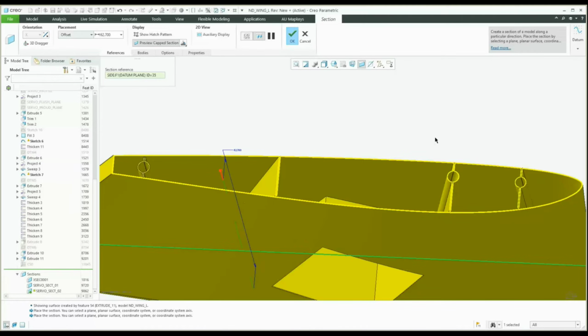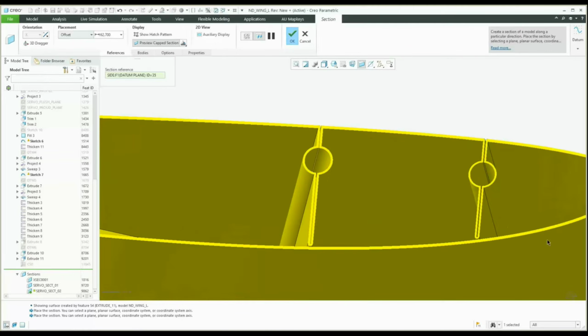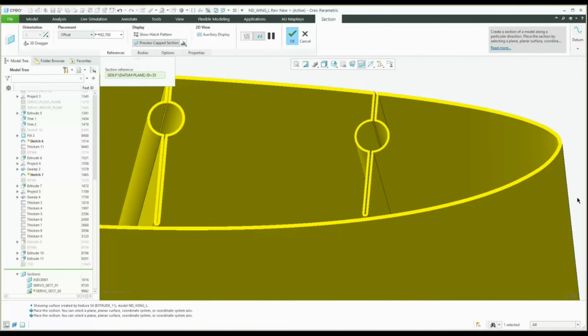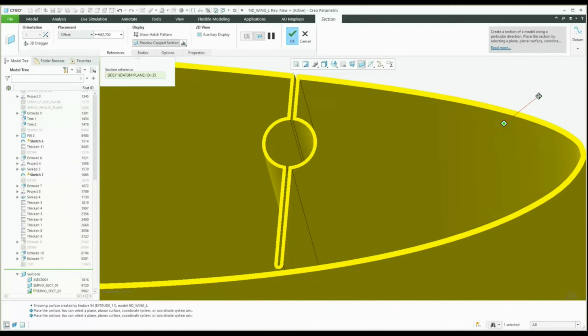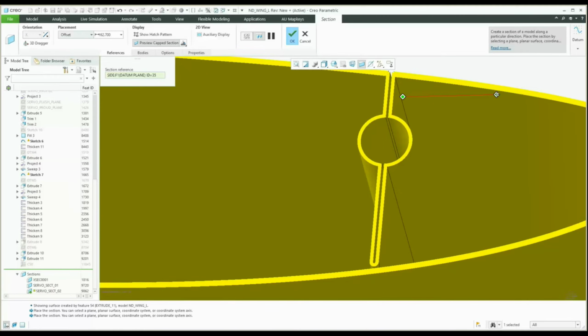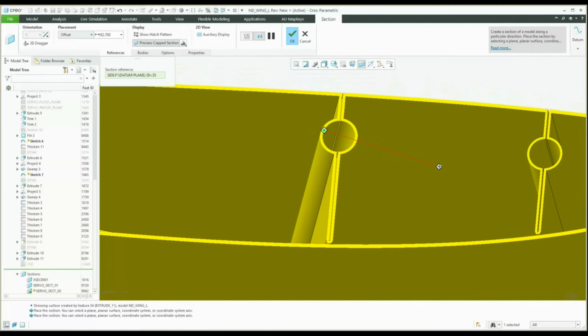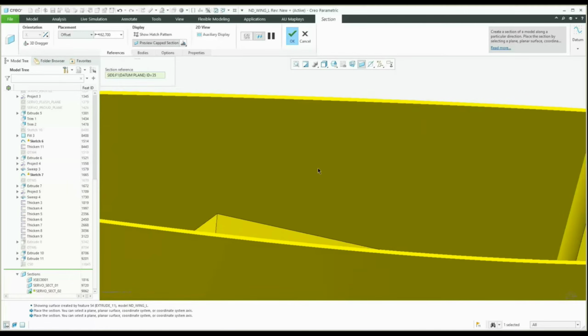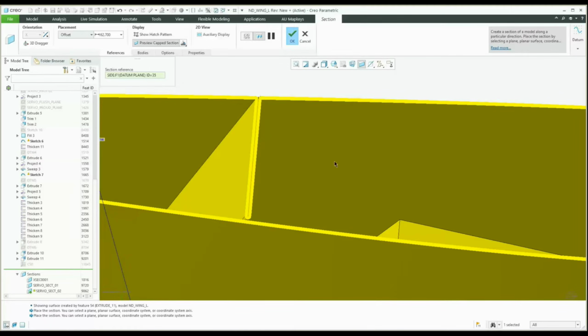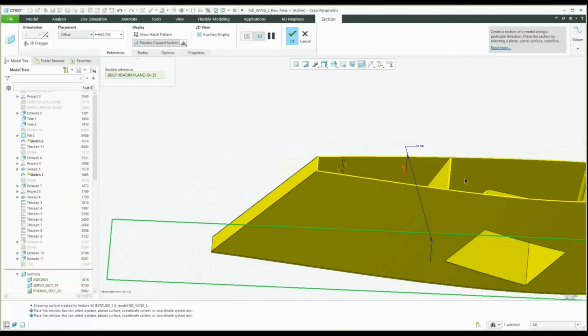Remember that at any print height, the cross-section needs to maintain an unbroken loop for the printer to follow. To add in a stiffening rib, for example, I did this by adding a surface that cuts in from the bottom skin of the airfoil and passes near the top skin, close enough that the two segments will connect when the printer lays down the beads. You'll notice I had to make this internal rib double-walled, so that the print path could return unbroken to the same point along the bottom of the airfoil that the rib originated.